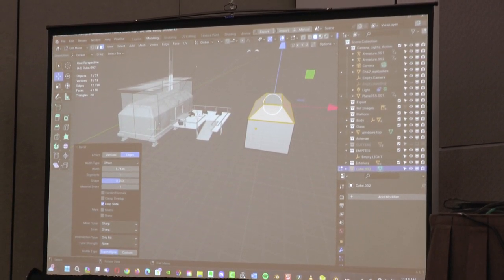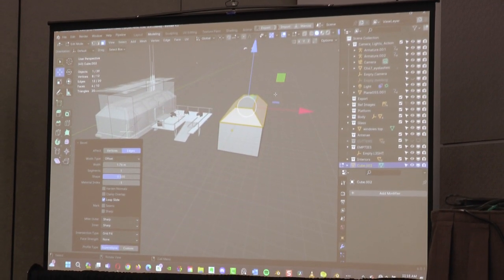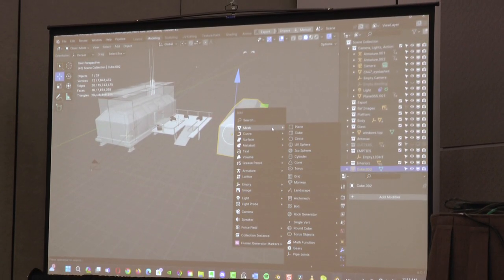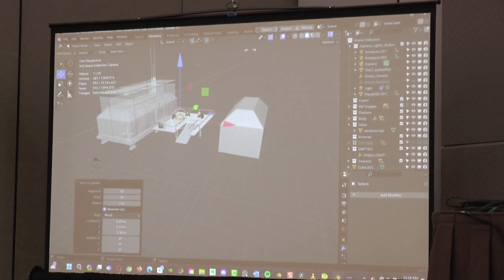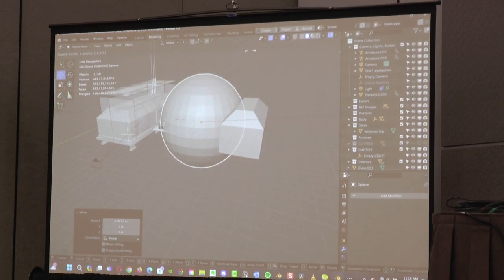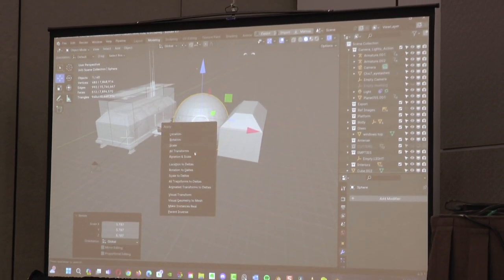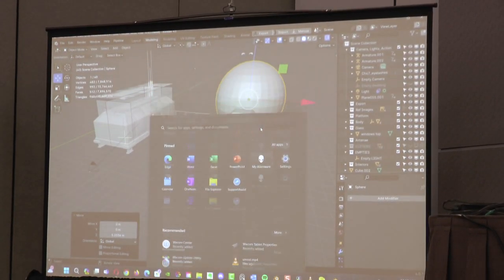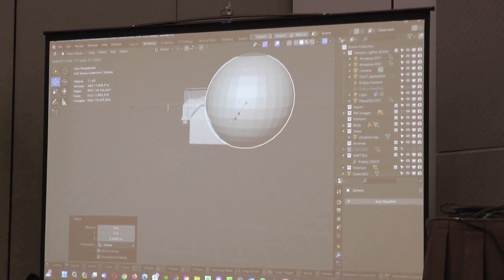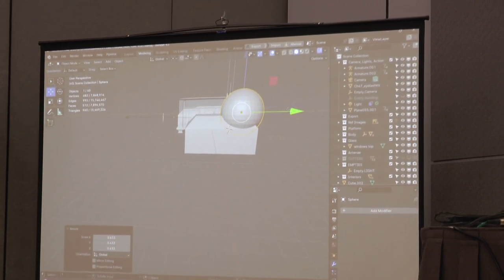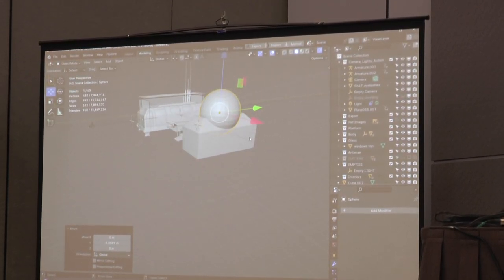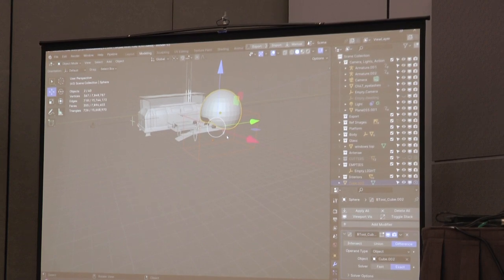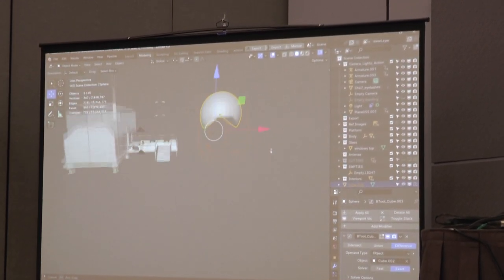I can create sophisticated shapes out of another shape. So in Blender, very quickly, I'm going to go back to my object mode. How about if we do, here, I'll get a ball. I'll get a sphere. We'll grab a sphere, select it, UV sphere. I'll bring it on over, scale it up a little bit bigger like so, okay? And I'm going to bring it on over like this. I'm going to take a big chunk out of this piece, right? I might even bring it down just a little bit smaller just to save time. All right, there we go. All right, so I want to take a big chunk out of this piece, select it, and then use a shortcut in Blender, Control minus. All right, and I'm taking the chunks out of this, right? So that's basically how Booleans work.